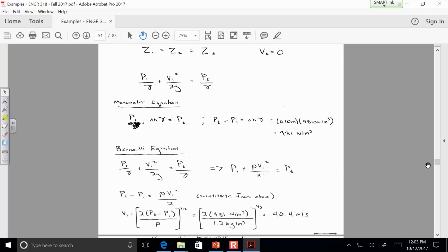And that opening of the manometer tube is a stagnation point, where all of the wind to the left of the stagnation point has velocity, but then when the wind dead ends at the opening of that stagnation point, the pressure instantly goes up a lot because all of the energy that existed as the velocity at location 2 is instead exchanged for an additional increase in pressure at location T, and then the assumption that the pressure inside the manometer tube where we've got gases is constant.